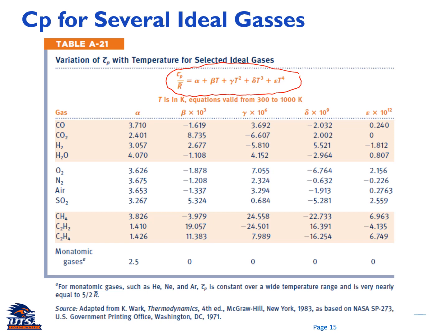So you can still use a table, but usually it takes time because you need to build code to do a lookup table, track the temperature, where is the location of the grid point, and so on. But with this polynomial formula, you can apply it right away in your code, and then the code will calculate Cp as a function of the temperature.